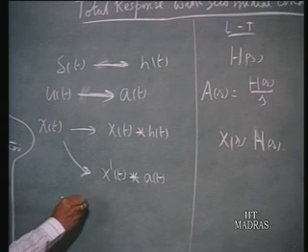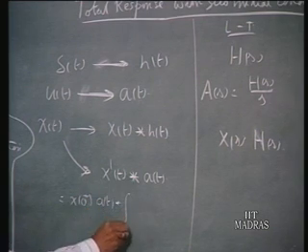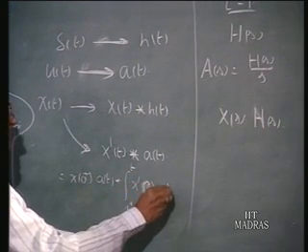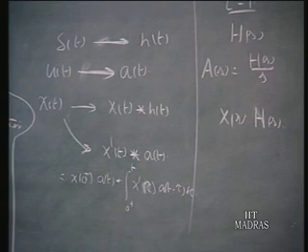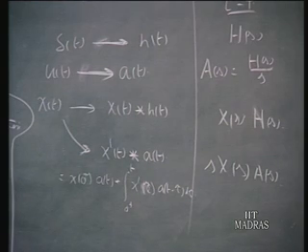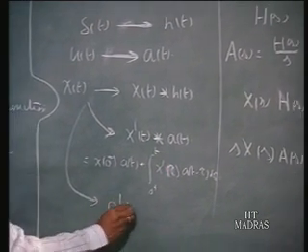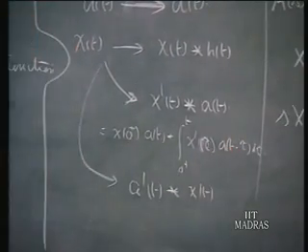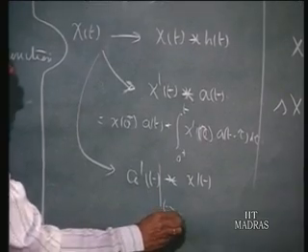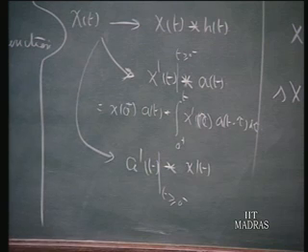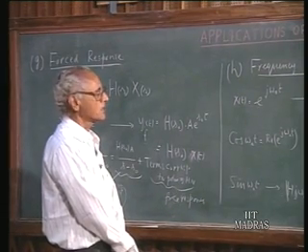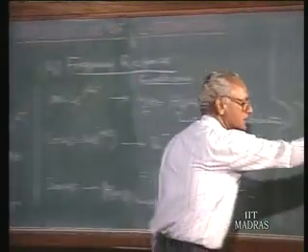The meaning of this is x of 0 plus a of t, plus the integral from 0 to t of x dash of tau times a of t minus tau d tau. All this we discussed in the last lecture. So in terms of Laplace transforms, we can write X of s times s. We also have an alternative representation of this. If you recall, you can write this as a dash of t convolved with x of t. That also has the same Laplace transform. In these two expressions, a dash of t and x dash of t, we are taking t starting from 0 minus, that is t greater than or equal to 0 minus. So that is how the total response of a system can be obtained from either the step response or the impulse response, or in general terms, this is how these equations will run.